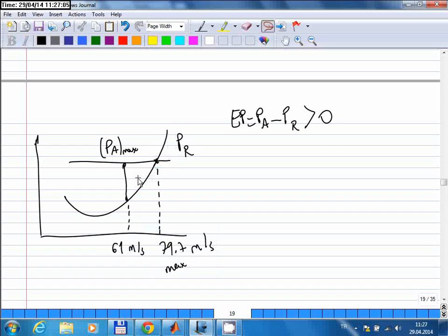So that's a very good point. So what I just said is valid only for steady climb. Otherwise, if you have an aircraft flying at maximum speed, and if the pilot increases the elevator angle to pitch up, then the equilibrium will be disturbed. Okay, so from that point on, it's not going to be an equilibrium flight anymore.